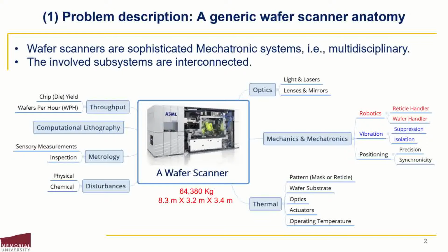Being immersed in manufacturing systems, a wafer scanner must be capable of handling various internally or externally generated disturbances. Projecting the operating conditions onto their corresponding energy domains helps, for example, in quantifying the induced vibrations, thermal stresses at the reticle, optics, and the wafer substrate, also looking into the tracking errors and synchronicity besides looking into the expected die yield. Therefore, in this study, we propose a multidisciplinary design framework of the motion trajectories used specifically in wafer scanners.